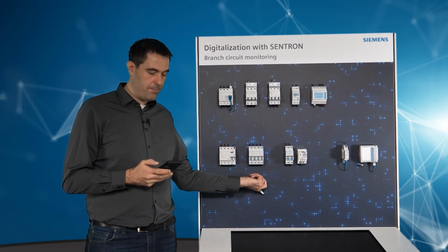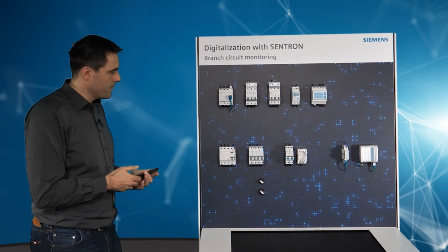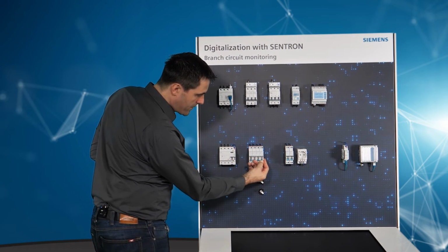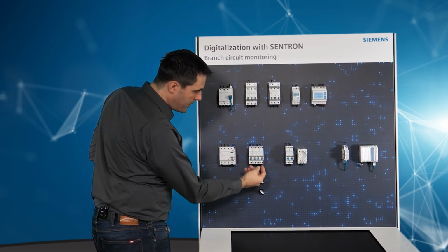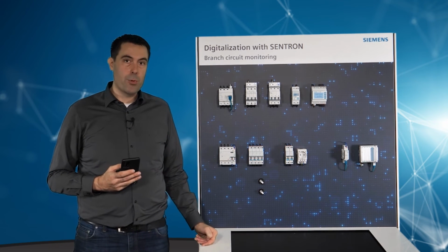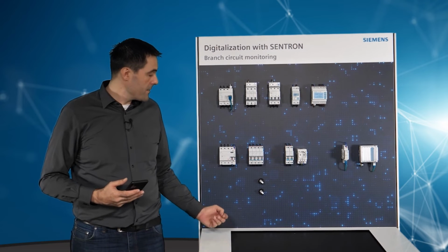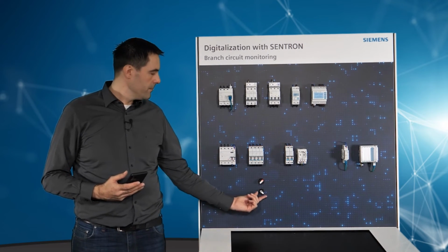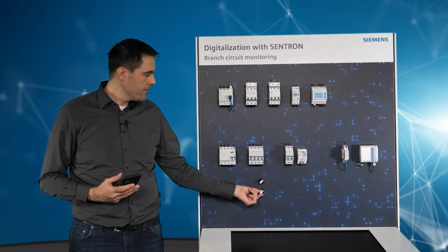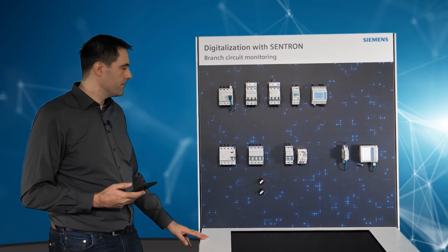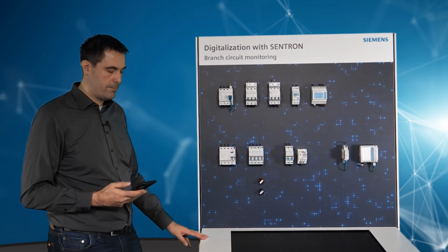Switching back to no load, we can reset the breaker here by pressing the button on it, and now it's still green. The other thing is let it trip, fan on, and go to second stage here. Now it also takes a few seconds until the breaker will trip.